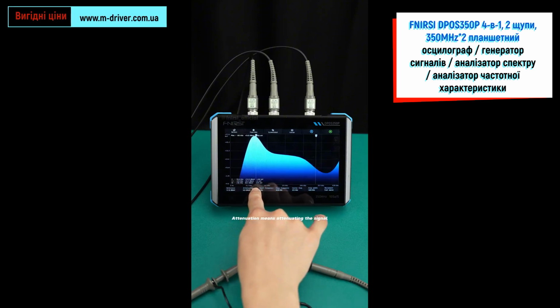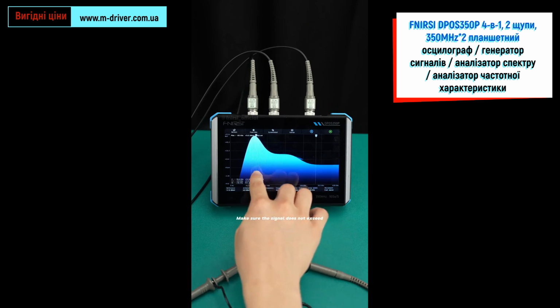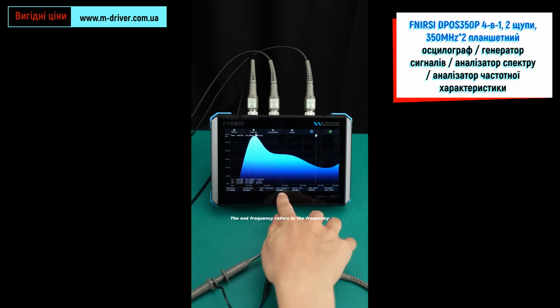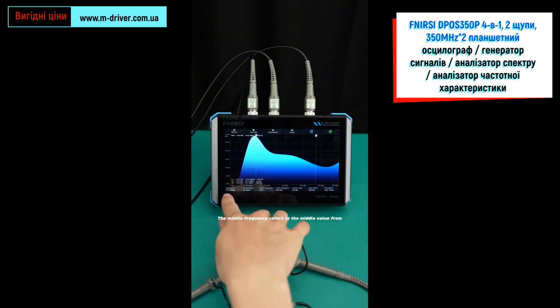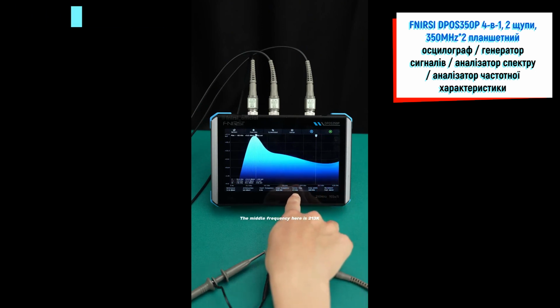Attenuation means attenuating the signal, the process of reducing the amplitude of a signal. Make sure the signal does not exceed the maximum processing level of the analyzer. The starting frequency refers to the frequency at which the spectrum starts scanning. The end frequency refers to the frequency at which the scan is completed. The middle frequency refers to the middle value from the start frequency to the end frequency. The middle frequency here is 213K.